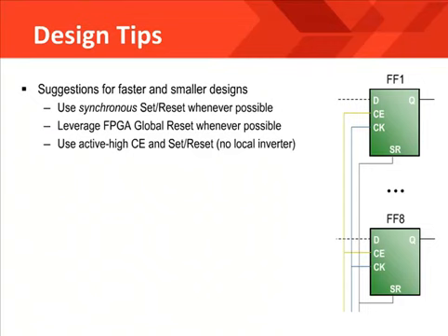Besides building synchronously, you should also try to use the FPGA's global reset functionality whenever possible. This will allow you to perform a global reset on your system using a dedicated routing resource. This will require the instantiation of the startup component from the Xilinx Unified Library that pertains to your chosen device family. Now, this will save you from routing a high fan-out signal to all of your FPGA resources, which is a significant amount of routing.